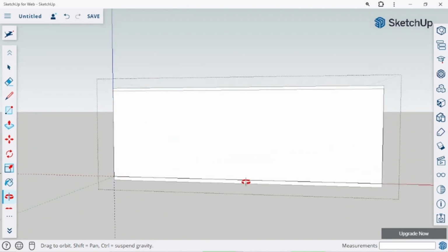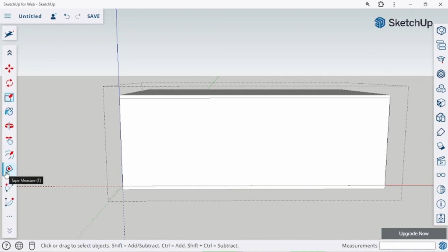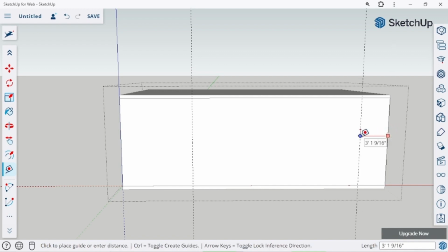This is what allows it to edit or add details to our design. So the next thing we are going to do is to click on our tape measure, click on any point of the plan, and you notice that it was on the blue axis. When I placed the cursor on it, it showed blue, meaning it's on the blue axis. So we move it to 8 feet. The next one, you notice that this one too is red, so that one will be 8 feet.